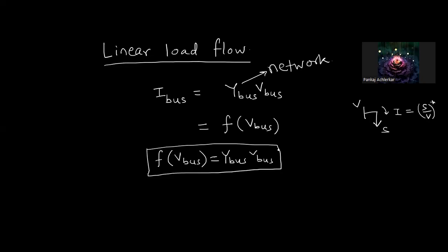There is no closed-form analytical solution that can be obtained for such a large number of nonlinear equations. So what we do is take some initial assumption on the unknown parameter. In this case, the unknowns are the bus voltages, so we initialize all the bus voltages at, say, 1 per unit and solve the equations in an iterative fashion.